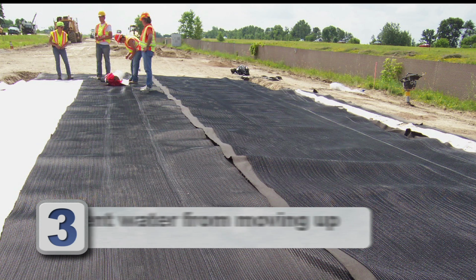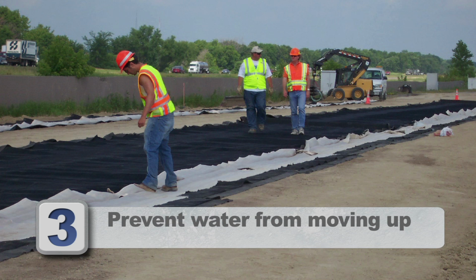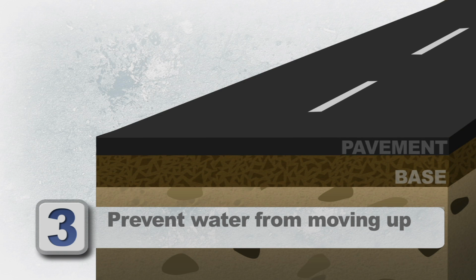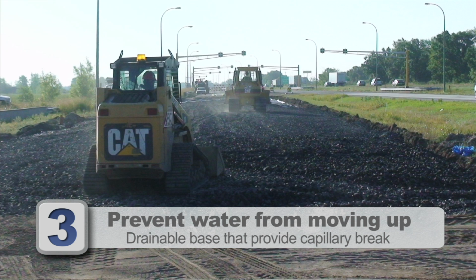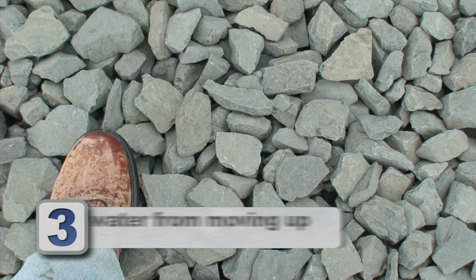The third method provides a capillary break that prevents moisture from being wicked up from the subgrade into the base. This can be done in several ways. One is to place a 12 to 18 inch thick drainable base, also called a rock cap, between a frost-susceptible subgrade and the base layer. Agencies specify rock cap material as coarse, open-graded aggregate with a low limit on fines content.